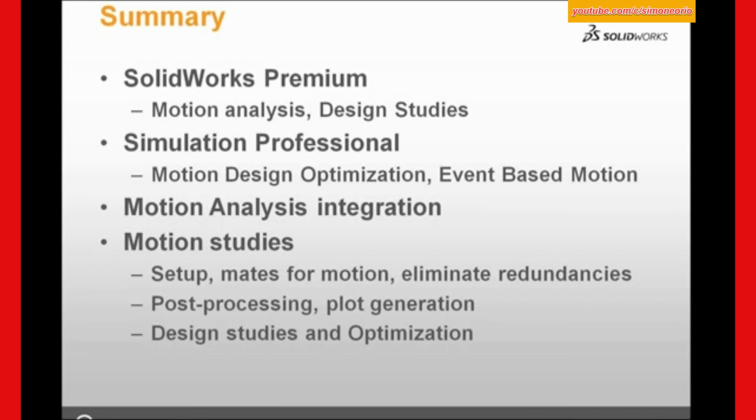I showed you the integration of motion analysis in our SOLIDWORKS window. It's no different than just working on SOLIDWORKS models. We have a very familiar interface as far as inputs and outputs with our feature manager. And last but not least, I showed you motion studies, setting up mates for motion, eliminating redundancies, and I showed you how to go through the post-processing, set up plots, and look at results for what's happening on screen. And then we finished with a design study and optimization.